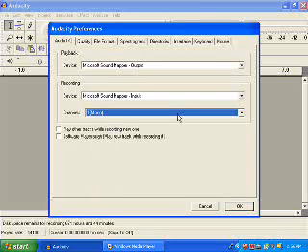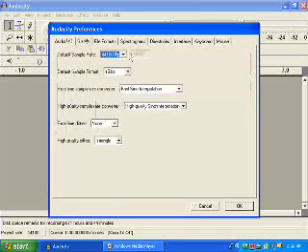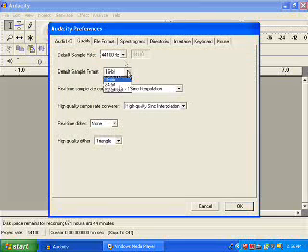Unless you're using 2 microphones, the stereo option simply duplicates the track, making the file size bigger without a resulting improvement in audio fidelity. Now switch to the Quality tab and choose 44,100 Hz as the default sample rate and 16-bit as the default sample format. Audiophiles will argue that higher sample rates and formats are better, but for spoken word, 44,100 Hz and 16-bit sampling works admirably, especially considering that the resulting output will be MP3. Ignore the rest of the settings on the Quality tab.